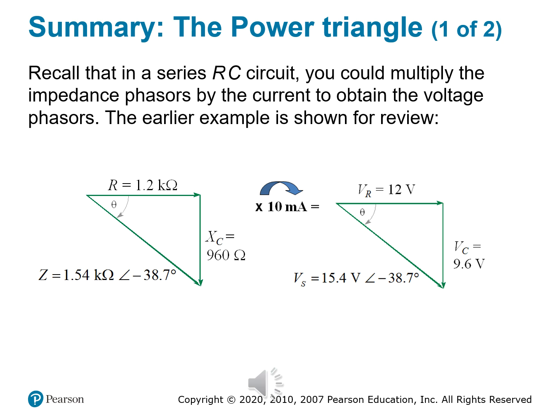And it's important because this triangle shows how power is distributed in your circuit. You have the real axis, and that gives us the resistive contribution. You have the imaginary axis, and that shows the reactive contribution from the capacitor. Again, this is just RC. Wait till we get to RLC, and you're going to have two contributions from the inductor and the capacitor. That is going to be crazy fun. But this is just RC. The angle still tells us about the power factor and how much current is leading voltage. So this triangle gives a voltage-based snapshot of where your energy is going.